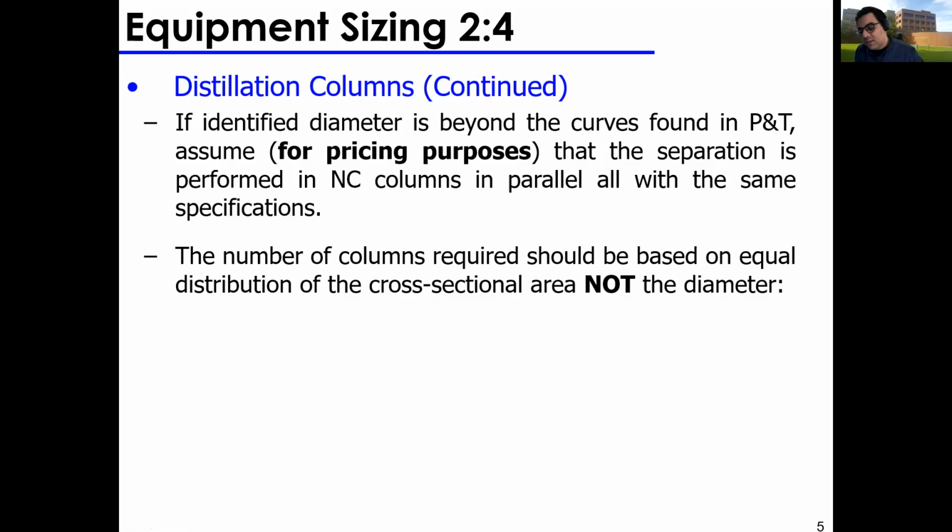However, in most scenarios you're going to deal with, you're going to deal with atmospheric distillation columns, because distillation columns are driven by temperature, right? They are temperature driven or thermodynamically driven or enthalpy driven processes. So a lot of the time in normal situations, they operate at normal atmospheric conditions, and you just play around with the temperature, play around with the reflux ratios to get the separation you want.